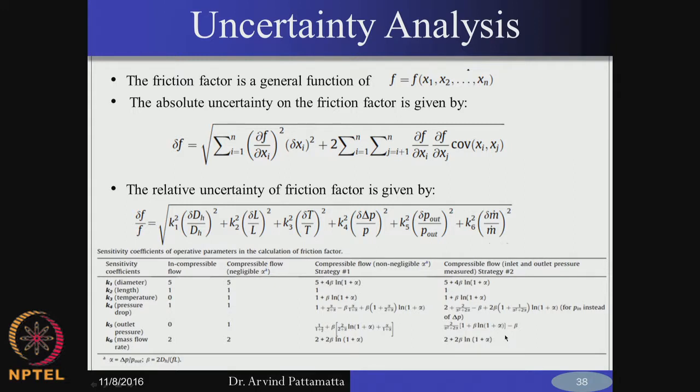Okay. So, finally, after doing all these measurements, a very important analysis is called the uncertainty analysis. You have to tell what is the confidence level of your experiments. Your experiments are never 100% accurate, because they all come with uncertainties in every stage. It could be uncertainty with your probe or the uncertainty in the setting itself.